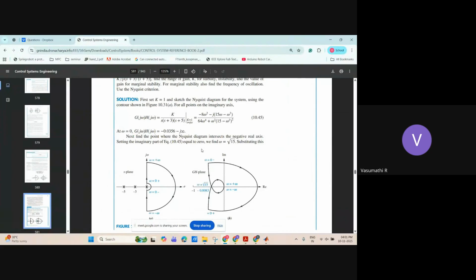It goes from minus 270 to minus 90. And it is not crossing minus 1. As you see, it is minus 0.08 only on the left hand side. So this is the open loop pole. It is circulating here, but not around minus 1. This is circulating somewhere before that. That's what we are seeing here in MATLAB also.